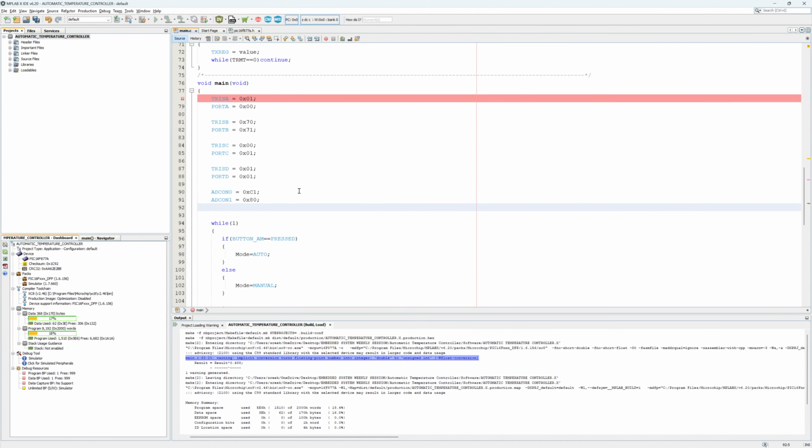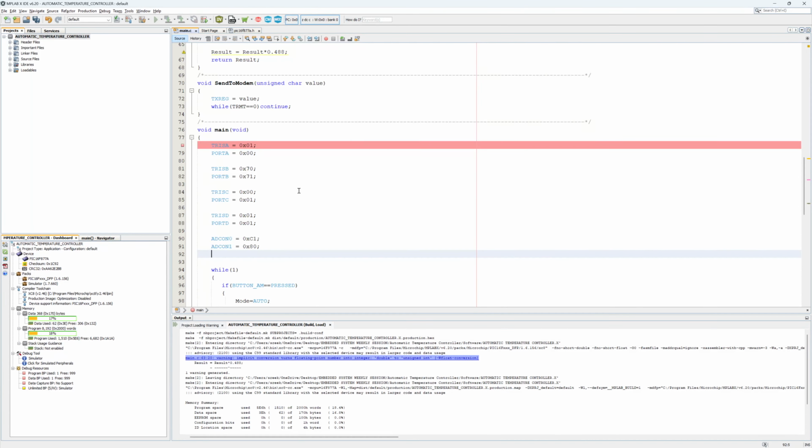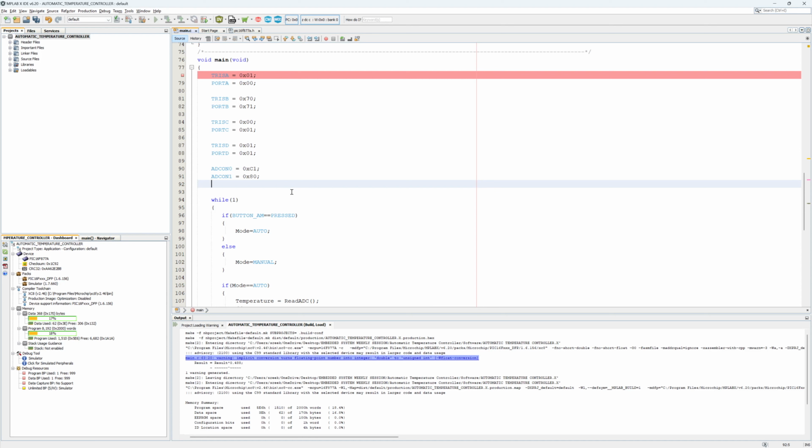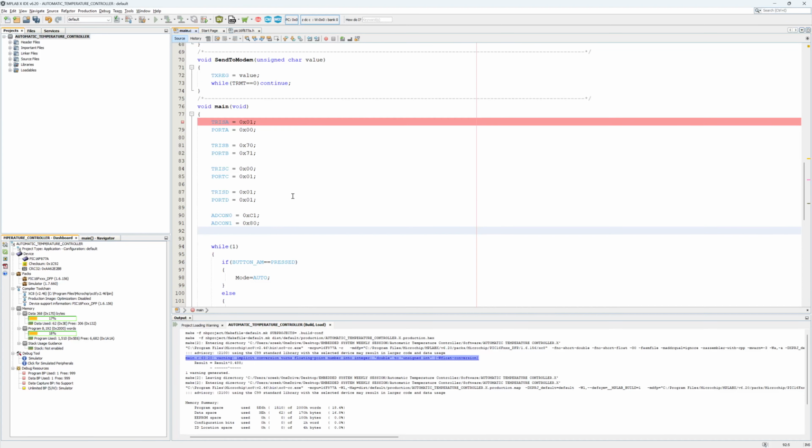For that, we need to debug the ADC in more depth. We need to know what value is coming out from the ADC after conversion. For seeing that, we need to use a debugger. Right now I don't have any debugger, so there is one more method to see the internal registers and internal variable status. For that we need to print the internal variable. For this purpose, we need to use the serial port of the microcontroller.